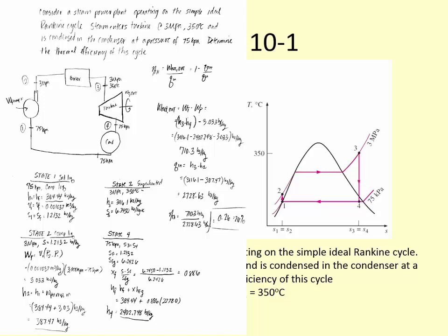If you're analyzing an idealized cycle, knowing that between state 3 and 4 is isentropic, you can find your other property values, figuring out how to calculate the quality at state 4. Then from state 1 to state 2, also isentropic, use the calculated pump work to solve for that second enthalpy, because you can't look it up directly. We don't have compressed liquid tables, and we don't know the temperature, so you solve for the enthalpy that way, if it's an ideal Rankine cycle.